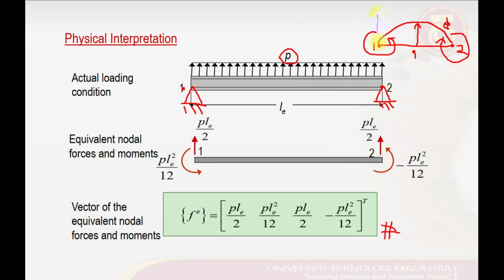we can replace this as well with a point load pointing upward at both nodal points, node 1 and node 2. So this is the physical thing that happens on one beam element subjected to a uniform distributed load. But somehow, positive conventions must be imposed to make the finite element analysis easy to construct and solve.